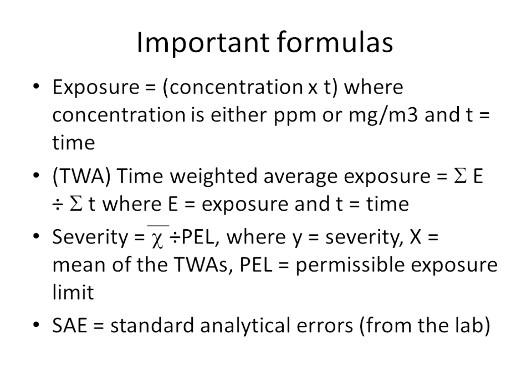And then, of course, you can weight that, and that's part of your time-weighted average, where you take the sum of your concentration times time, and you divide it by your sum of time. So you divide it by the amount of time that the worker was there, and that's your time-weighted average exposure. And yes, that is your actual exposure versus your 8-hour exposure. You can only use 8 in the denominator in place of the sum of time if you are sure that the worker was not exposed at all during the time period in which you weren't there.